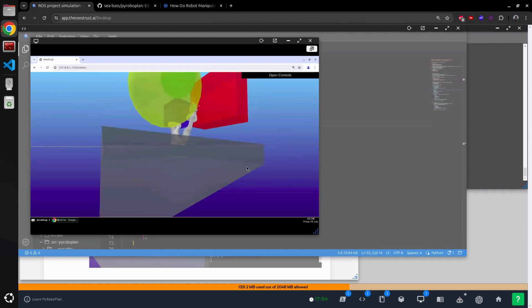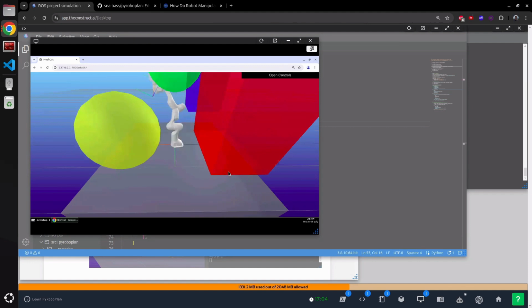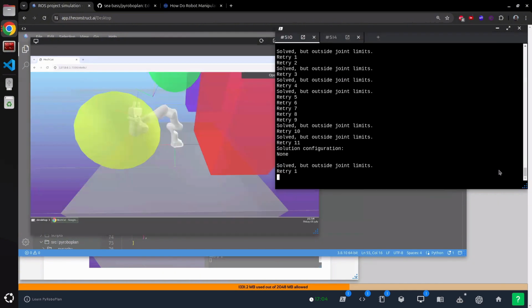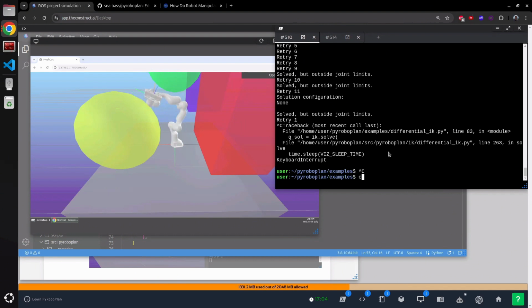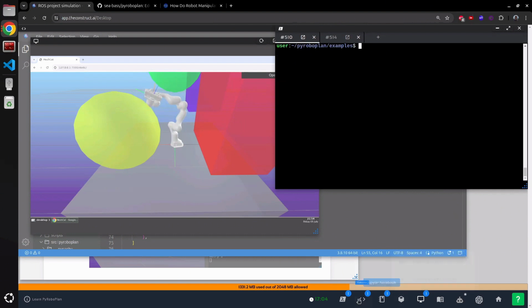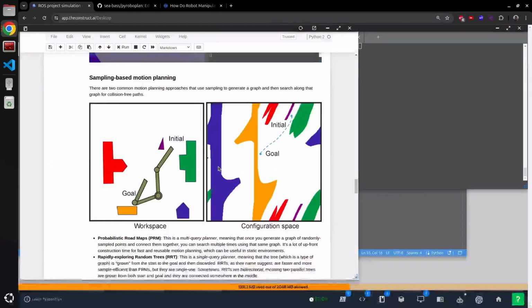Okay, so inverse kinematics is one thing. Again, this is just showing you the progress of this optimization to move to your target pose. Suppose you've already done your inverse kinematics, right? Next, we're going to get into the actual path planning, which I think is probably the one that we want to spend most time on. So one of the classical ways of doing motion planning, and this is actually one of the key features in MoveIt, is this notion of sampling-based motion planning.